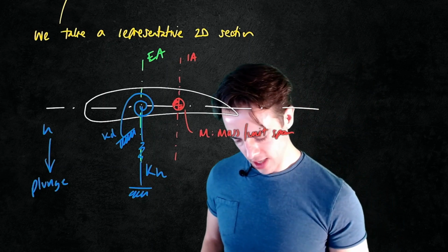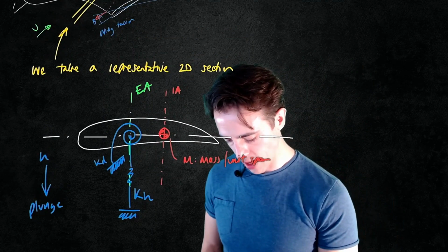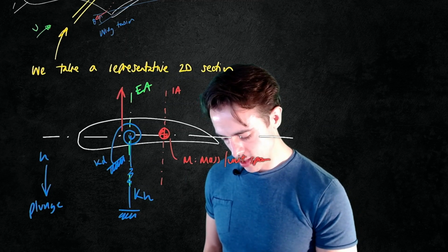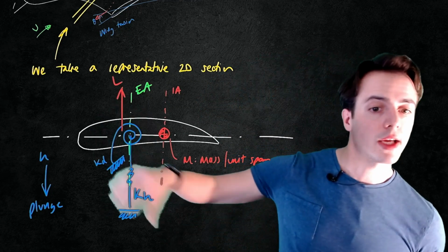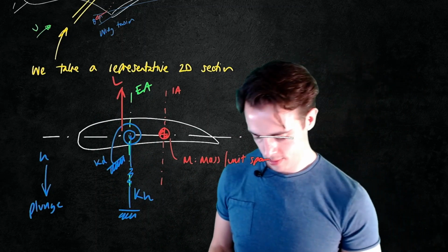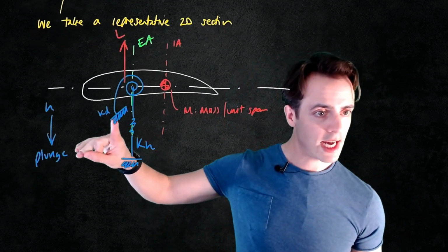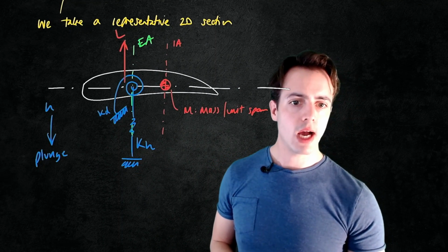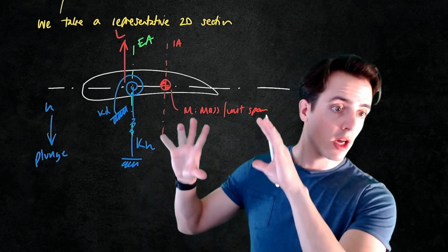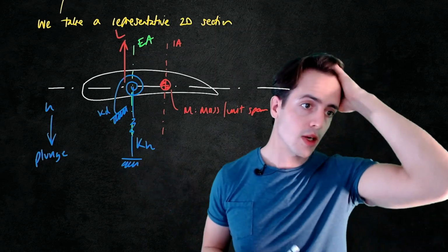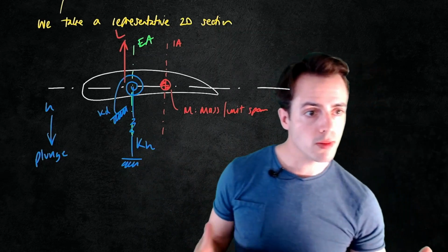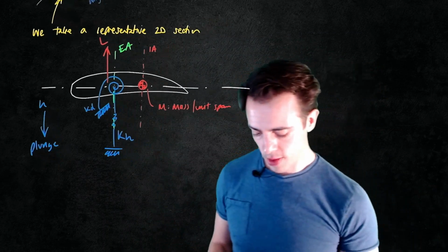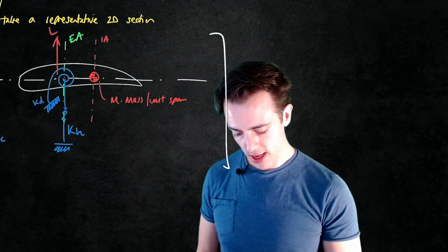And then we've got these aerodynamic loads that we can look at on the wing. So we would say that wherever our aerodynamic center is for this particular aerofoil, we would have the lift working on this wing. So we've got torsional stiffness, Kα, and we've got plunge or bending stiffness, Kh. So that's our simplified mathematical model that we're going to use, and we will be using this next week when we look at a divergence model and when we do a model for control reversal. This is probably the simplest this model could be. We could complexify it.